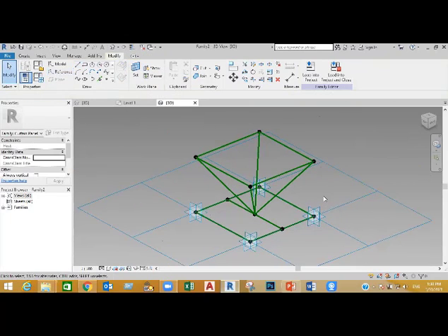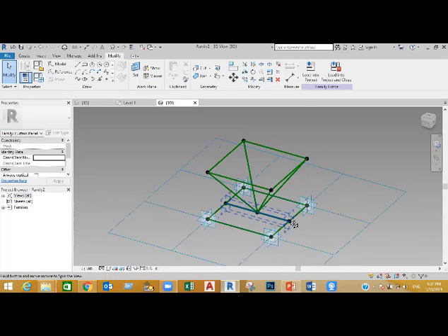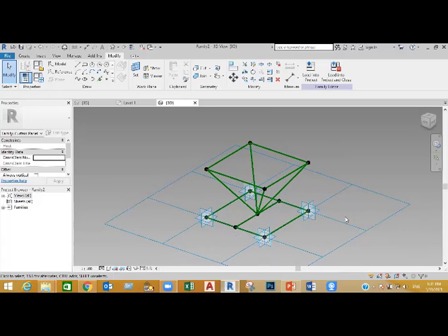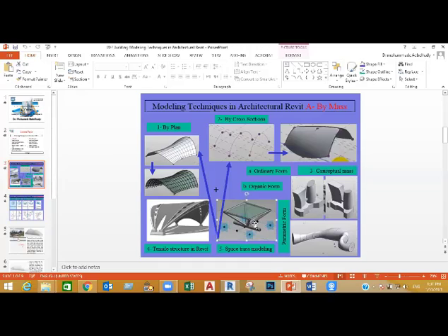Okay. So again, the first step we put points, model points. These model points we make an offset for them. After I made the offset, we connected them between each other by using a reference line. After we connected with the reference line, we made a model point in the middle, a model point at the middle, and after that connected with a line and connected a reference line between this point and the middle of this one in order to have this unit. Nice.